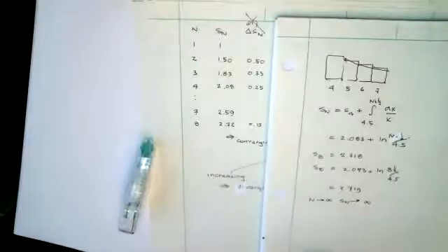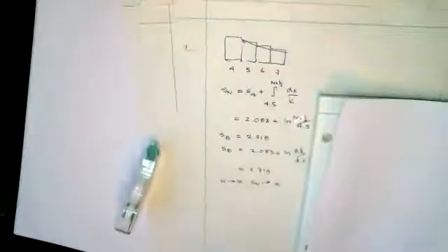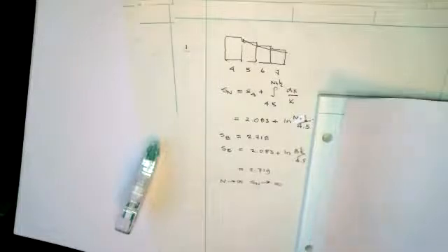I still see it practiced by finite element engineers, and part of their reason is, well, it's too expensive to do the other one. Well, not if you start with a coarse enough mesh. Okay, that's what you've got to do. So this is what we're going to do for the convergence check.